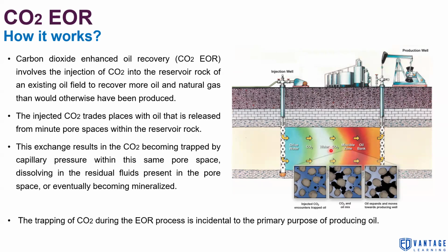So what happens is when we inject CO2 above a minimum miscibility pressure, CO2 can achieve miscibility with the oil bank, thus enhancing oil swelling, because oil volume keeps increasing as CO2 is a separate phase coming and mixing with oil. So this oil can be produced and later can be separated from CO2. Again, the same CO2 can be used through the injector well.